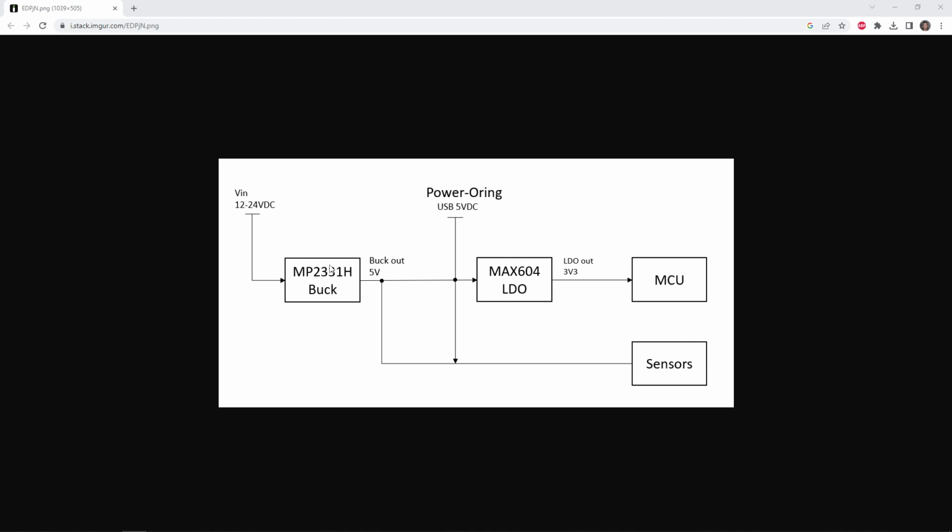The buck converter itself is of course a lot more efficient, oftentimes over 90%, and therefore this high input-output voltage differential is no problem, even at higher currents typically. Keep in mind though that using buck converters in your design, as this is a switching converter with magnetic elements, these will typically be more susceptible to EMI problems than, for example, a design that just uses LDOs. Of course, this is a very big generalization as it depends on other circuitry as well, but keep that in mind when comparing buck and LDO converters.